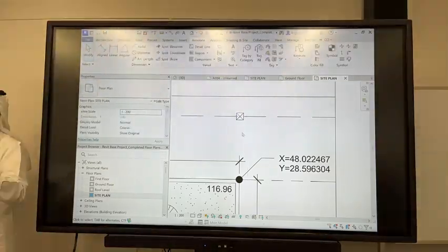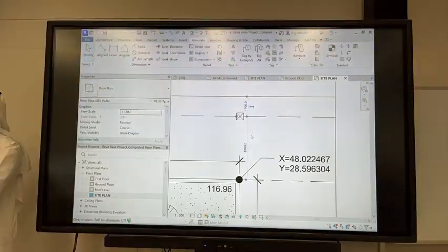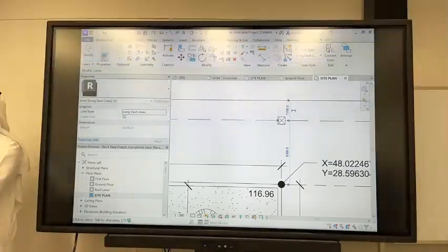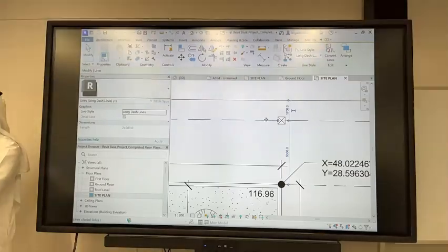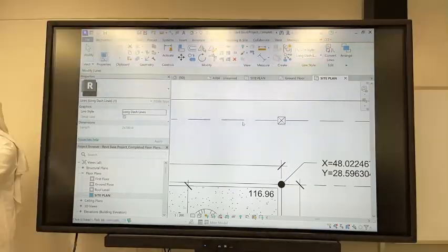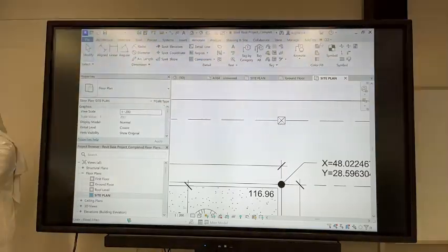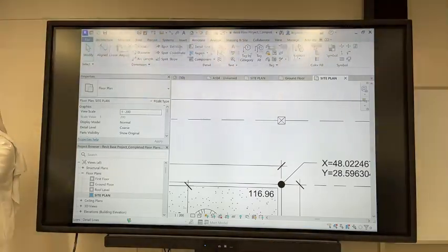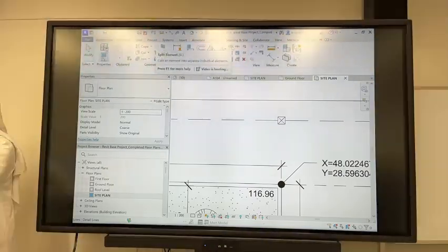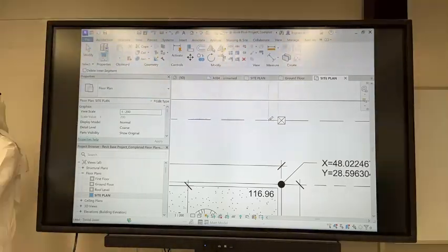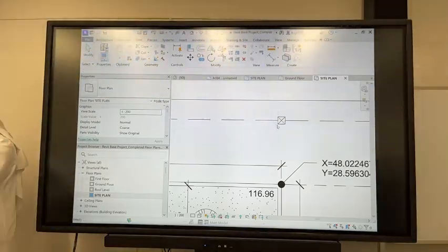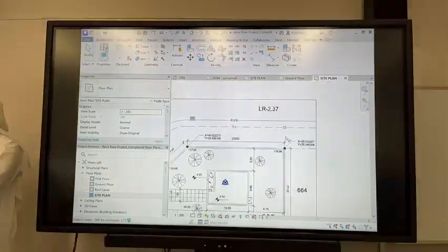Okay, so you break the line, you split it. Remember, you go to modify, split, SL. You split the line, you get an exact point when you do split line. Either you drag or you draw two lines, either way. You cut it and then you add the box and you draw on the other side.